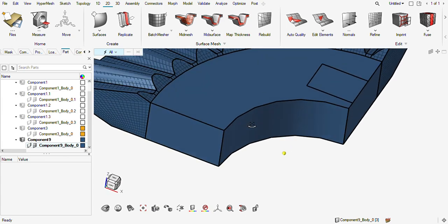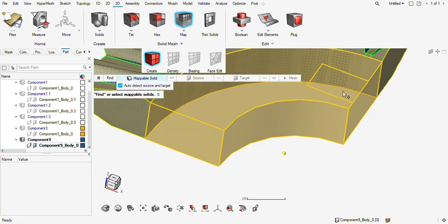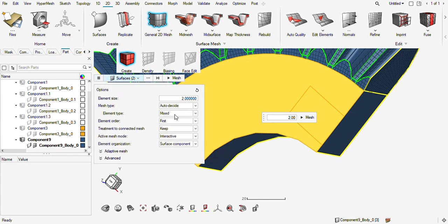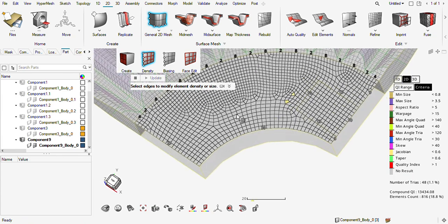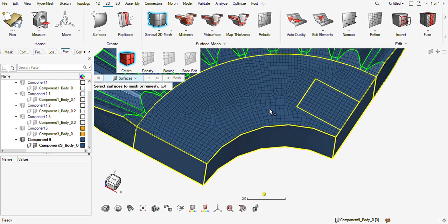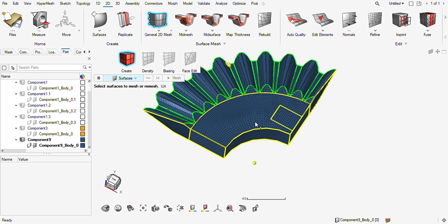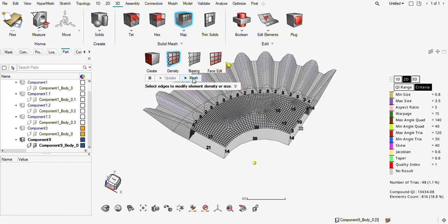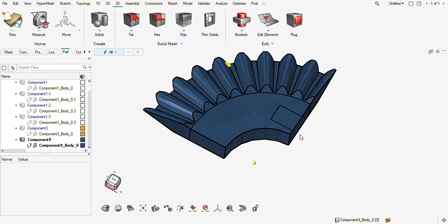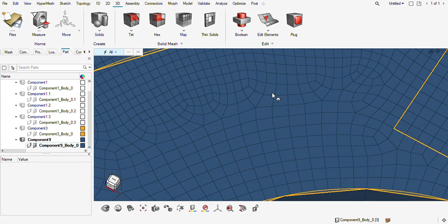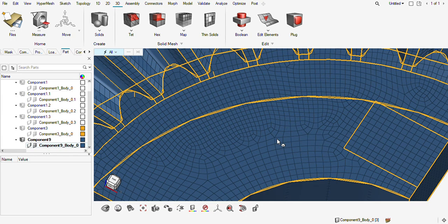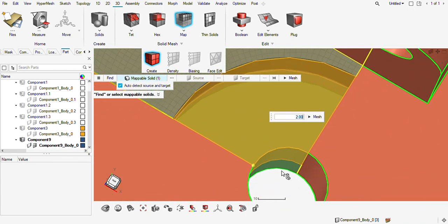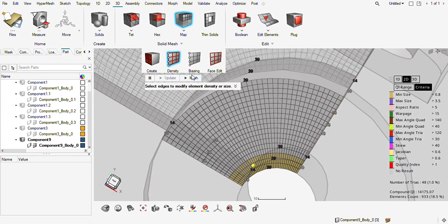Okay. Now this one I need to directly do the solid meshing, as the face meshing is okay. We'll try to do it this way. Simply use the map option here to batch mesh it. We can allow some rotating triad here. You can even use the structured mesh here. Okay, now simply go to here and this one and just click OK and click on mesh.